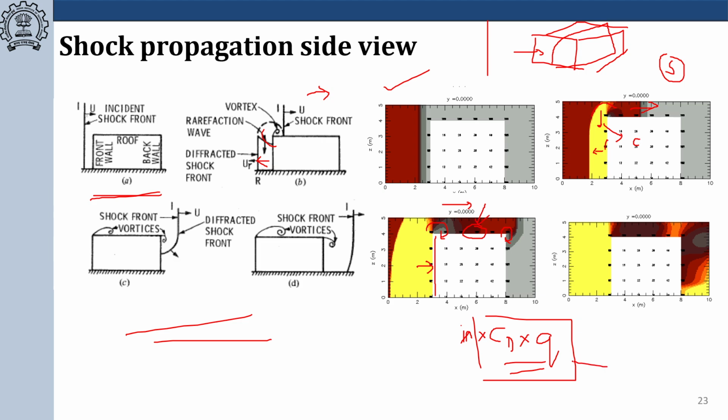You can use that pressure to compute the loads, or you can obtain it from the simulation. If you have the velocity term, then you calculate the drag pressure as the drag coefficient times the dynamic pressure, and you will be calculating the pressure on the surface. Or you can get this pressure history. It's not always the reflected pressure. Here you have a drag pressure on the rooftop and sides also, and you have to use that pressure to compute the loads on the sides and the top of the structure.